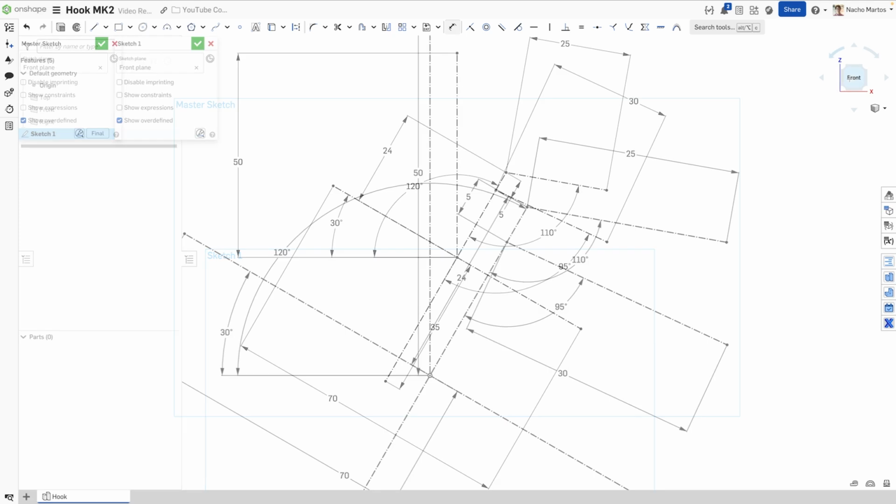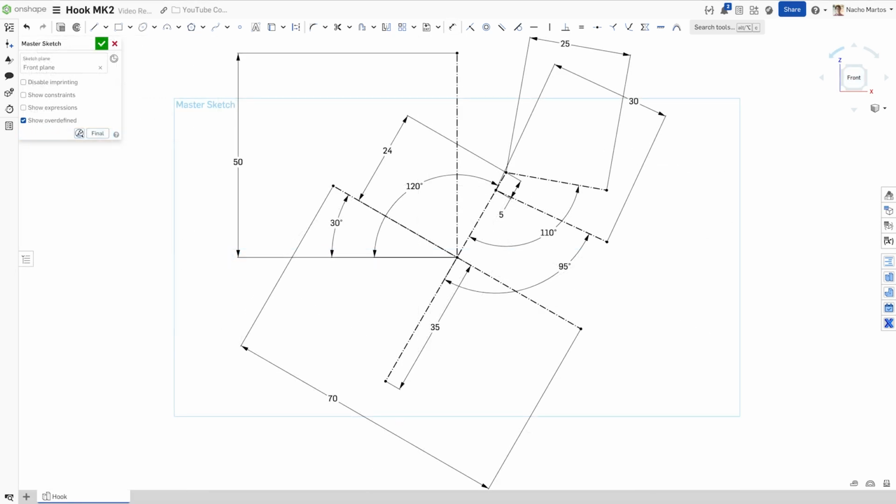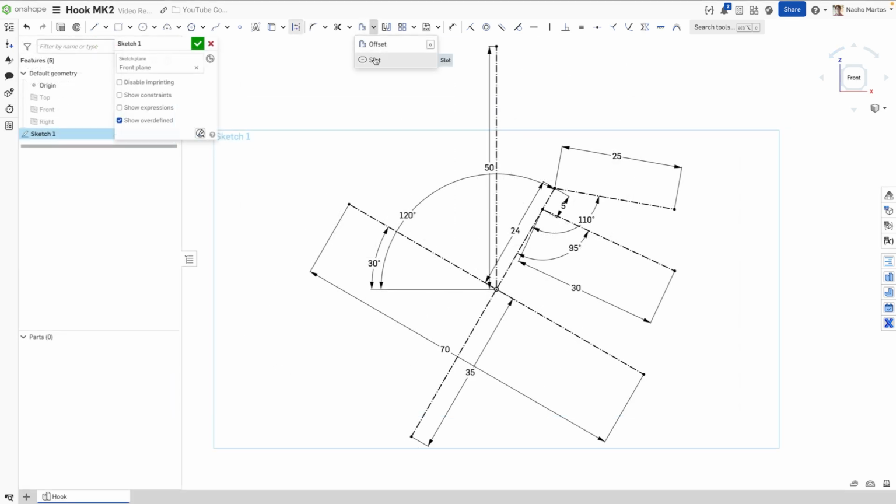All right, so these are the key dimensions that we're going to be focusing on today. I'm going to try and make this drawing as clear as possible. We can just travel here and find that slot, and we're going to use this line as the key slot. We can select this dimension that the slot brought out, and we want this slot to be 25 centimeters. So that's going to be the diameter of the arcs that define the slot. We can accept that, and that's it.